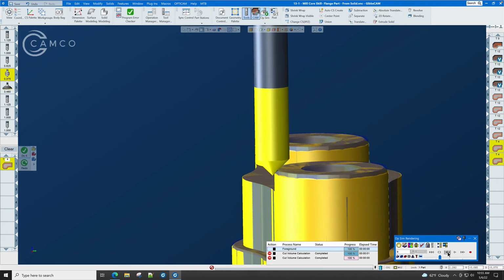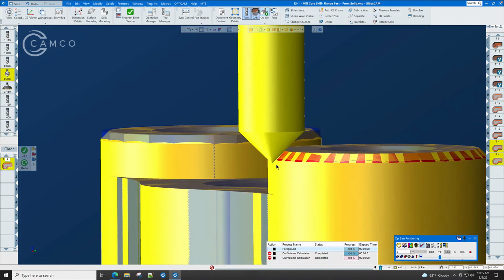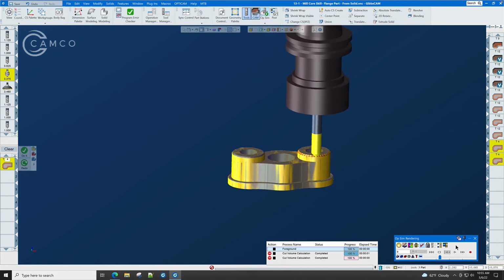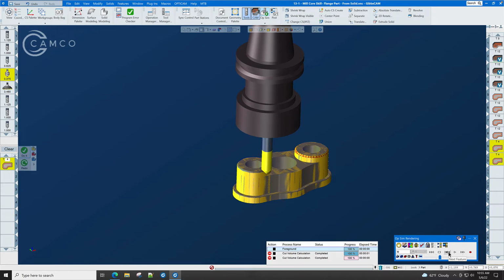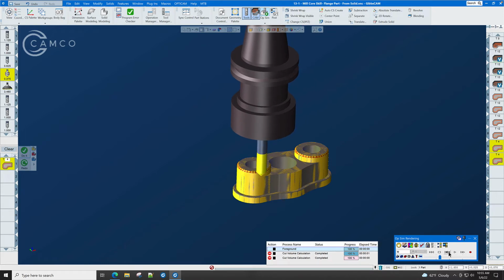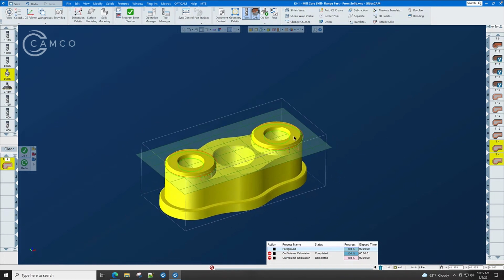We're looking to make sure that we're not using the top of the tool and the bottom of the tool, because we don't want to leave a mark on the part. We just cut that chamfer, and now we're going to single block through the other chamfer. All done. Now the chamfers are cut. It's time to cut the chamfers on the top of the holes.